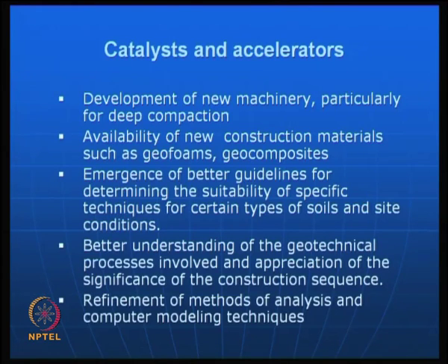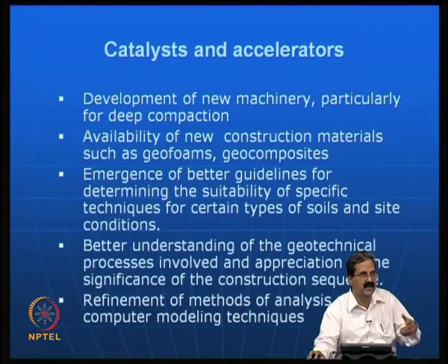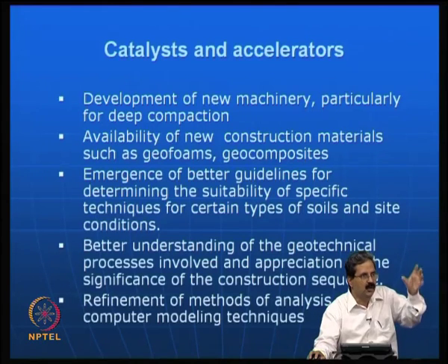So, people have been working with new machines nowadays, even for mixing and monitoring and anything. So, this development of new machinery, in fact, has been a big area. Then particularly for deep compaction, you will see that shallow compaction has some equipment like road rollers and all that. You know about shallow compaction, you have seen soil compactors. But for deep compaction, where the soil has to be compacted to about 15 to 20 meters, you need to have some more machinery, where you make a borehole, then put some system into the soil. Say for example, I was talking about stone column. Stone column, you have to make a bore, then put the stone inside, and then slowly withdraw that.